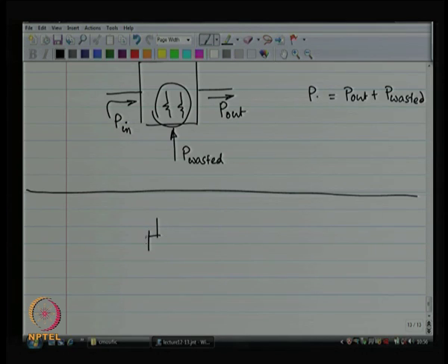So, I have got my MOSFET, it is a 3 terminal device. There is power coming in at DC into the drain. There is power coming in at the high frequency into the gate, right, there is current, there is voltage. So, power is going into the gate.